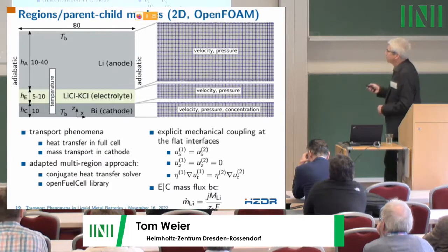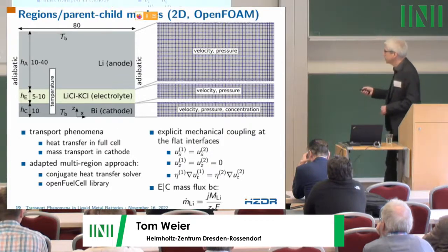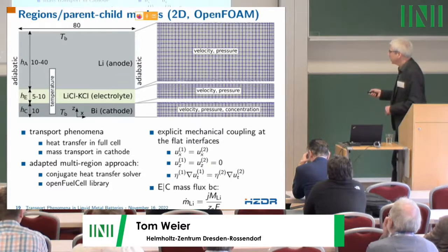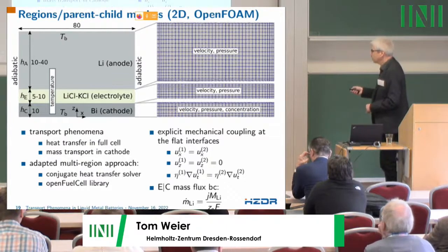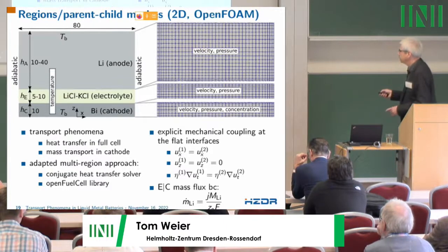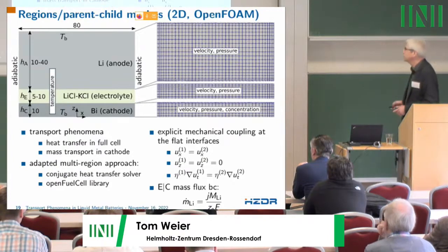And that's important, this mass flux that we discussed, and the mass flux is described by Faraday's first law. It's directly proportional to the current density we apply, the molecular weight of the metal, the Faraday constant, and how many electrons are given away or taken up.